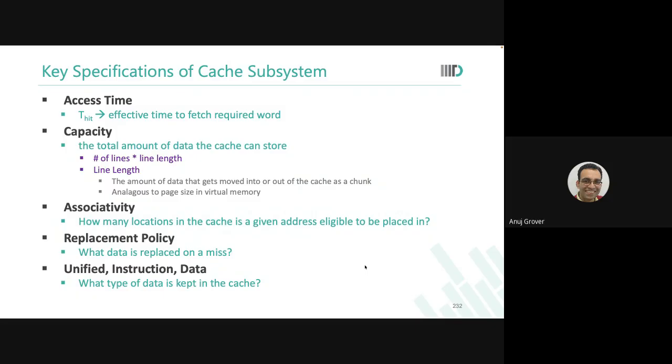Always it is. Do the sets have the same address, or what? Like how the LSB can. So, very good question. He's asking, suppose I have a 4-way set associative memory, will all the 4 have the same address? In a 4-way set associative memory, the LSBs would be the same. But there are 4 different sets of MSBs that are possible now. The tags can be different. But the LSBs will be the same.